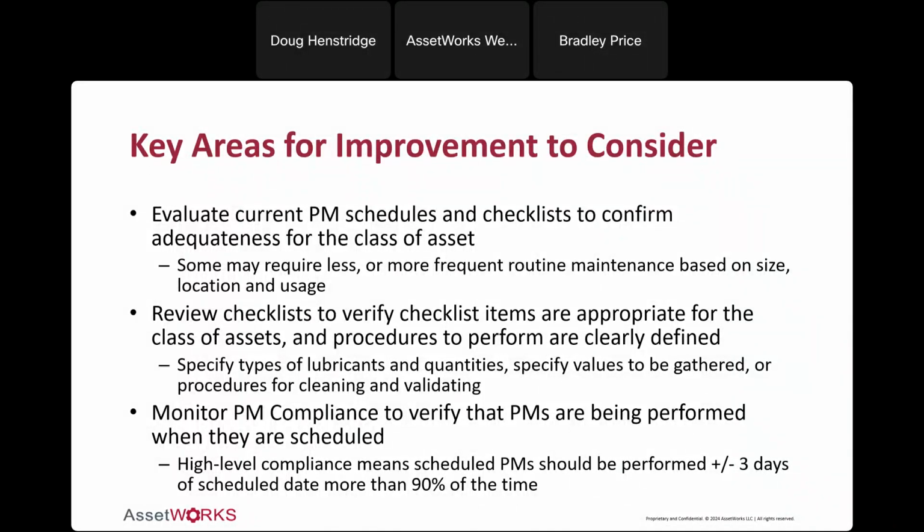So I worked with an agency a few years back, and they ran a treatment plant, and as a specific asset in the plant or in the process aged and its condition deteriorated, they adjusted the inspection schedule. So if something was brand new and was of a very high or excellent condition, the inspection schedule on it was a little more spread out, right? And then as it aged and as they started noticing its condition deteriorating over time, they would shorten it up. So it would go from 6 months to quarterly to monthly as it aged until they replaced it.